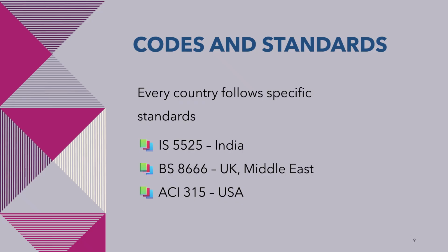As a professional rebar detailer, one of your first tasks is to identify which standard the project follows before you begin detailing. Never assume. Always verify the project specifications and general notes. Professional tip. One of the first things I check when starting a new project is the applicable detailing standard. Shape codes, bar notations, scheduling methods, and even drawing conventions can vary between standards. Knowing the correct code from day one helps avoid mistakes and saves a lot of time later.